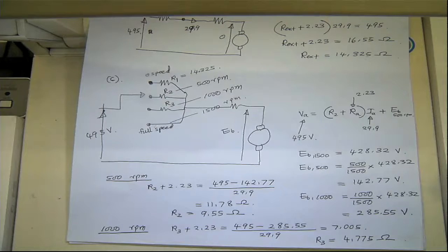If you're doing that on a high-powered motor, it's wasting a lot of power. But it's just the starting transient, so it might be a couple of seconds. It prevents burning out the motor or tripping or damaging the supply, so it's a kind of protection. It's not really worth getting voltage regulation just to start, unless you want speed control, like different speeds.